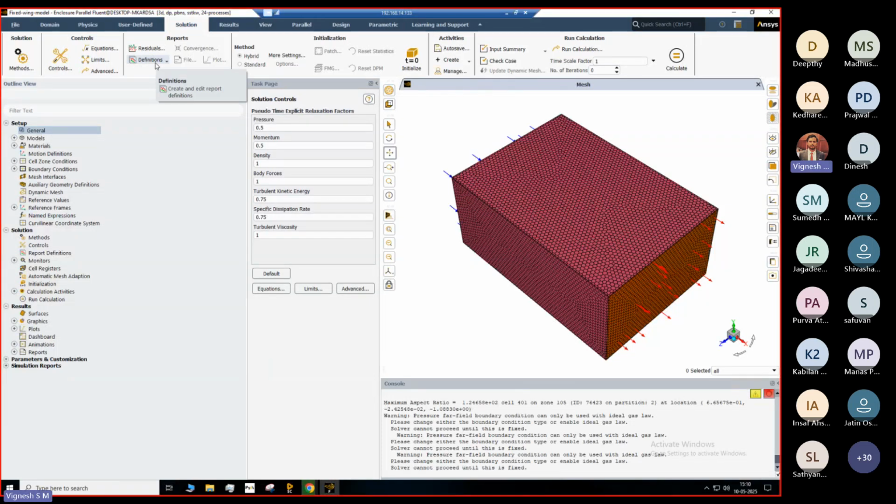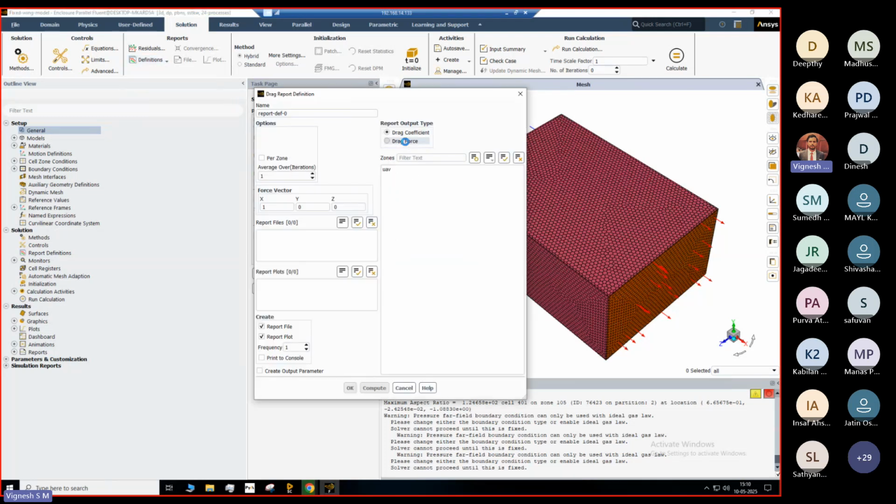While defining the problem, I told you that I want to look for the lift and drag forces on this UAV. So I'm going to define it. I want a force report during each iteration. First thing I'm looking for is drag. So I'm clicking drag and need a drag force. If you want, you can also keep the coefficient. I just click the UAV. The drag force acts in the X direction, so I make sure it's activated on X. So this is going to be my drag force. Done.